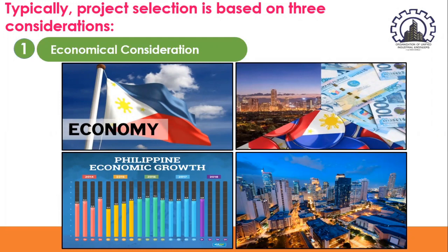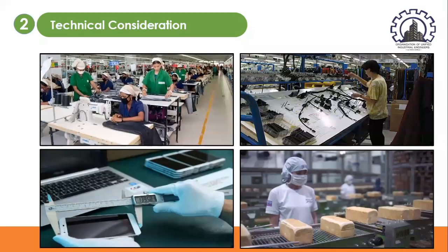Problems could be large amounts of scrap or rework, excessive material handling in terms of either cost or distance, or simply bottleneck operations. On the other hand, technical considerations may include processing techniques that need to be improved, quality control problems due to method, or product performance problems compared to the competition.